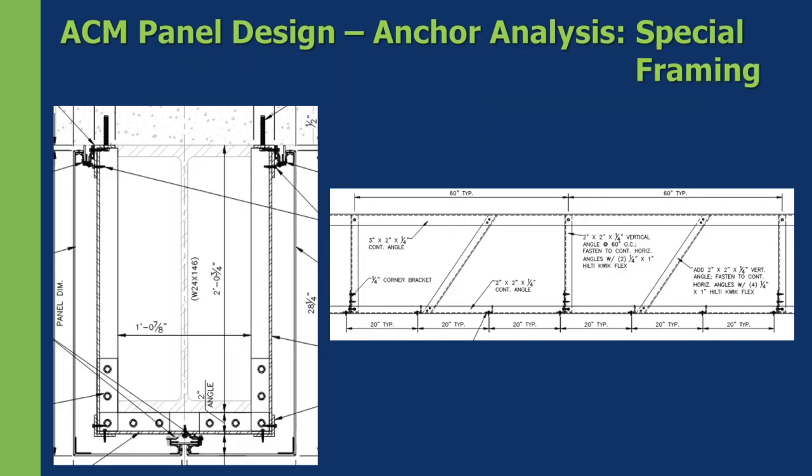Another area on this project that an engineer here at JEI did was we can't anchor into the beam. So we have to create a structure to wrap around the beam that we can anchor the panels enclosing the beam to. Watch out for areas like this because unanticipated framing will cost money. Specialty framing like this will cause engineering time and additional engineering analysis that will cost additional money. Just be aware of these areas.